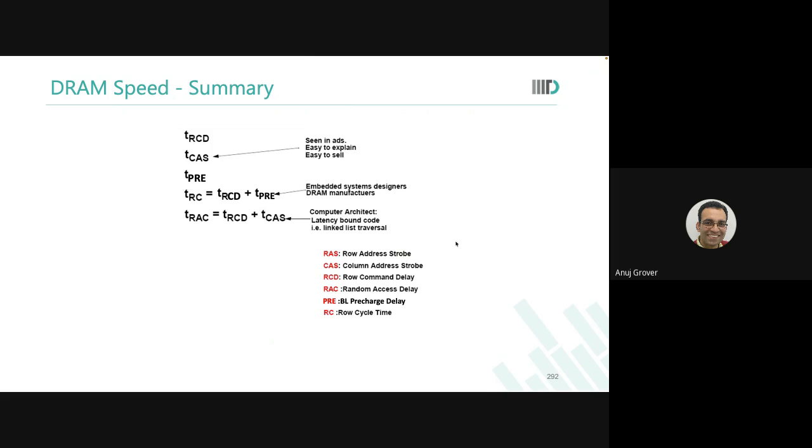Each of these race conditions will change because now the word line has a much longer vertical side to walk and then come horizontally, whereas recharge can just walk horizontally straight away. And the recharge RC has not changed. Word line delay has increased, recharge delay has not increased. Something is going to give. Some new marginality, some new race conditions will appear. Or whatever race conditions you already identified, they will move differently and you will have to recharge everything as a designer.